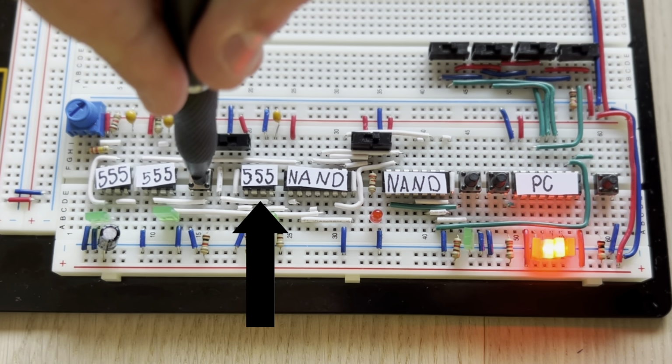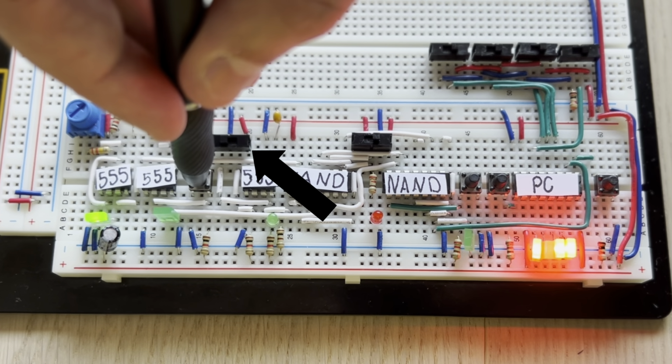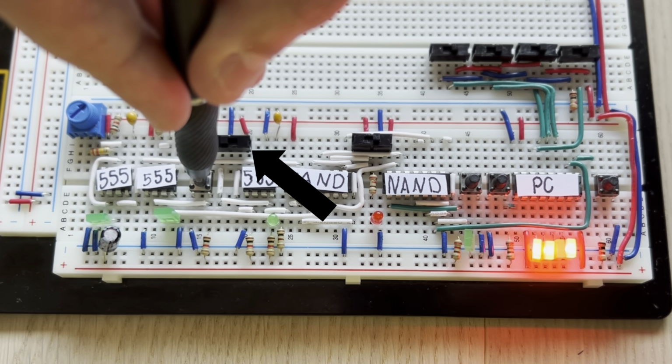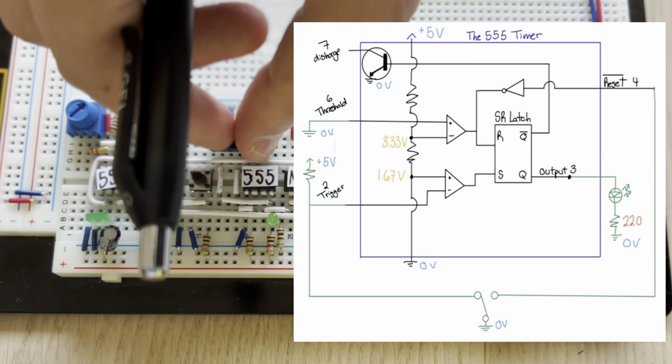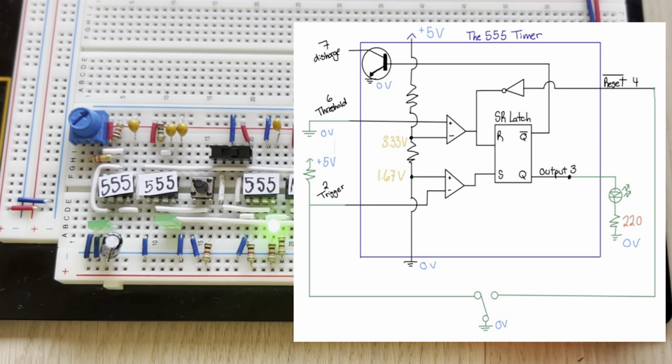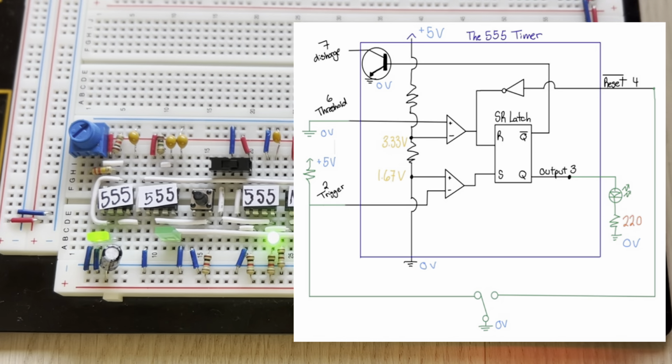Lastly, a bistable 555 has 2 states, high and low, and it switches between them based on external triggers, with this being a slide switch. When a slide switch is used in a bistable 555 timer, flipping the switch can toggle the outputs between high and low, essentially acting like a flip-flop with no automatic return to the original states until the switch is flipped again.